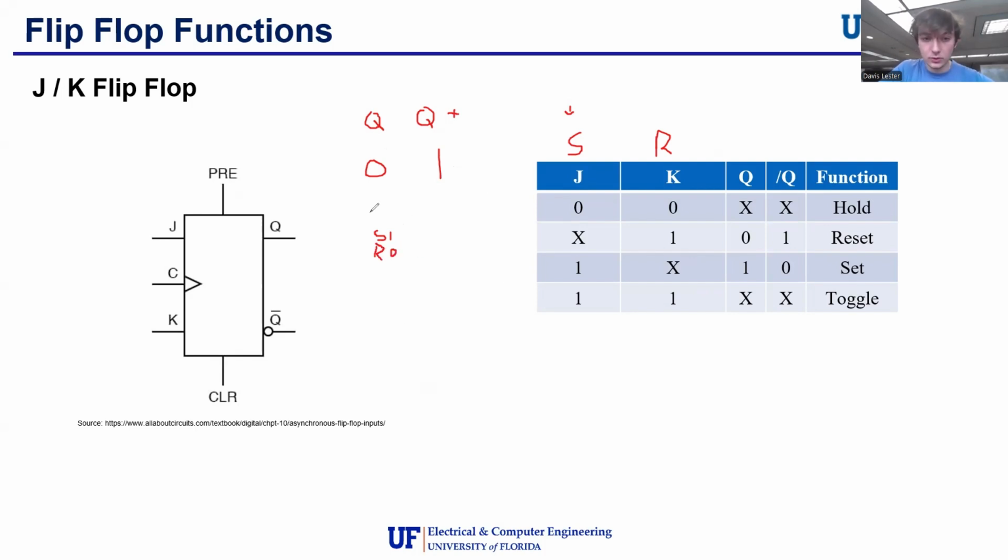Okay. So this is what we would normally do. But however, we're using a JK flip-flop, so we have the added functionality that we can toggle. And so if you look here, we're going from 0 to 1, which is actually a toggle, which means that S1 will stay as 1, but we can also have R be 1, because again, we can toggle, right?